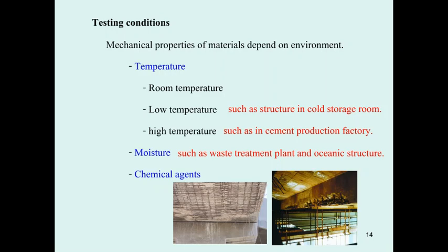When it gets rusted, the steel will spall the concrete out like this. And then the steel reinforcement is going to deteriorate very quickly. And when the steel deteriorates too much, this kind of structure may fail.